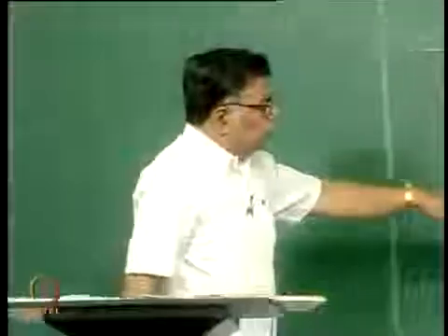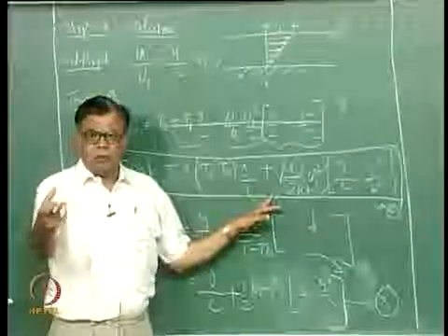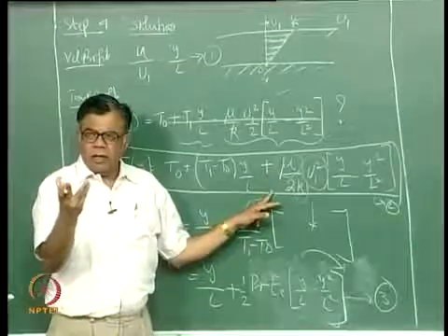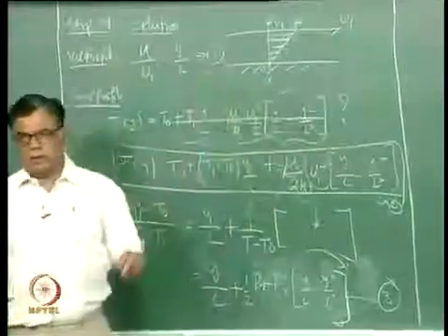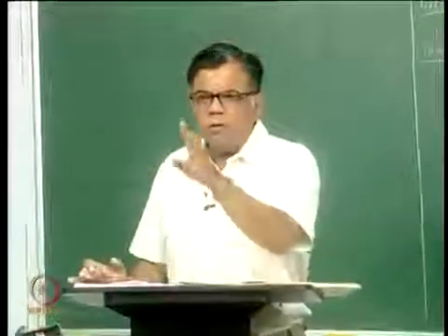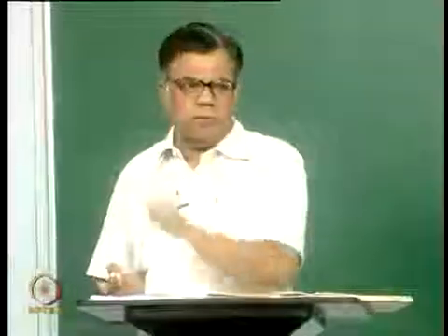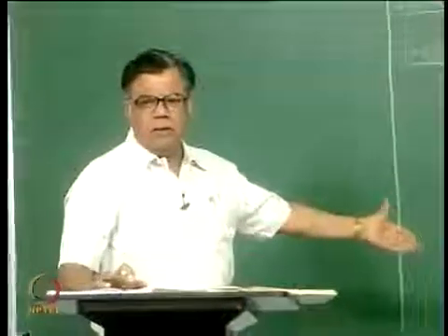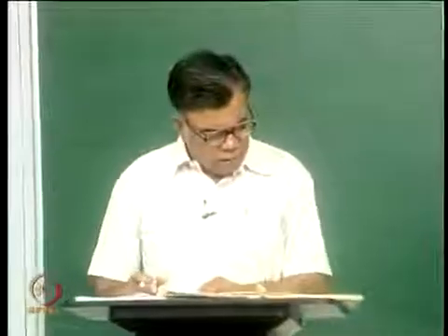If you go into the previous one here, this actually is much more, according to me, representative of the situation, mu u1 square. We are talking about viscous dissipation. If you look at only u1 square, it is kinetic energy, that is also right, but the real effect is the viscous dissipation, mu u1 square, and mu is already here in the Prandtl number, so you can try to give it a physical significance. This is extremely important.